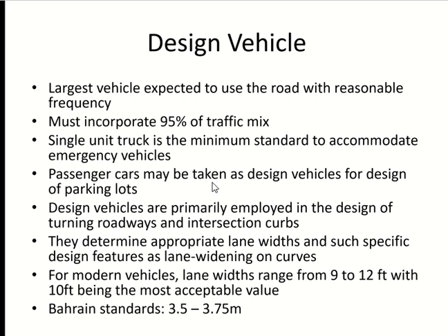According to the size of the vehicle, you will decide your lane width, right? Vehicle is bigger, you need more space. Clear? Also, your turning and something which we call lane widening. The lane width on the straight road is less than the lane width on the turn.